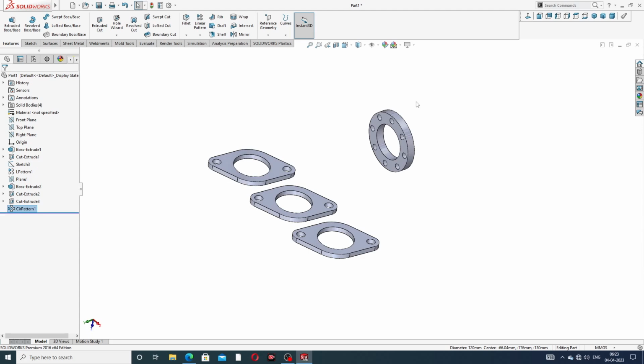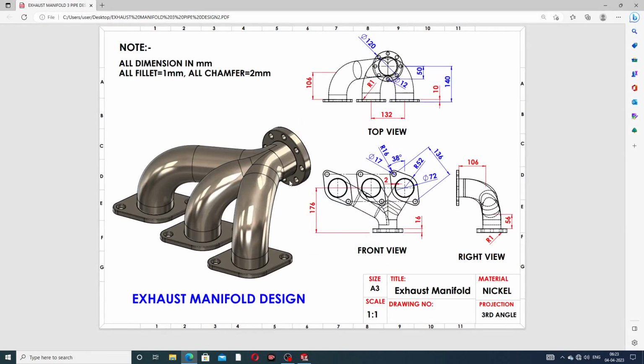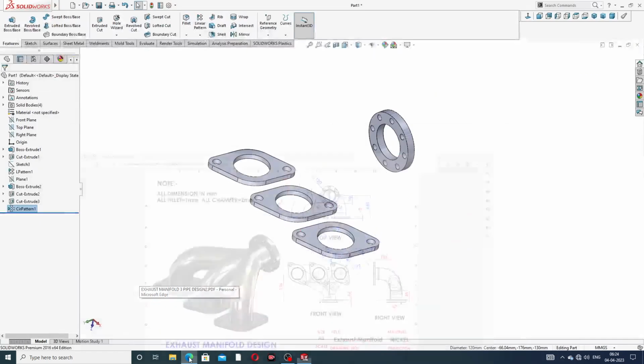And next is drawing a pipe. The pipe connects this body to this. This is very important. The distances are 160 millimeter, 106 millimeter, and 56 millimeter, and use a fillet. The fillet is 98 millimeter, and this one is 68 millimeter, but this is not mentioned here. It is a missing point, and use a fillet.